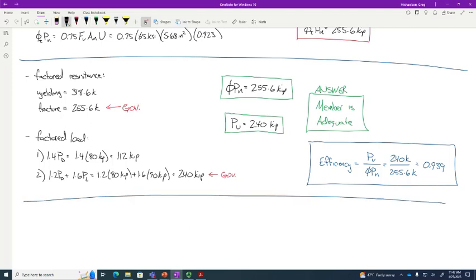Last thing I want to do real quick is a quick slenderness check. This will be real quick. How long was the member? 40 feet, which is 480 inches, if my mental math tells me it is right. We need to look at r min. What is r min for this member? Is it rx or ry? ry. And what was ry? 1.61 inches.